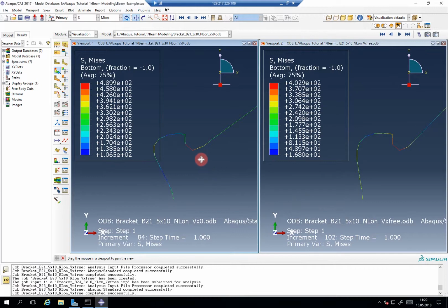So you can definitely see, by allowing the movement of the point to the right in horizontal direction, that you allowed this vertical part of your beam structure to stay more vertical, whereas in this case, where you forced it to remain on this vertical line, the deformation had to be reflected by this part of your beam, where in this case it was definitely moving to the right.